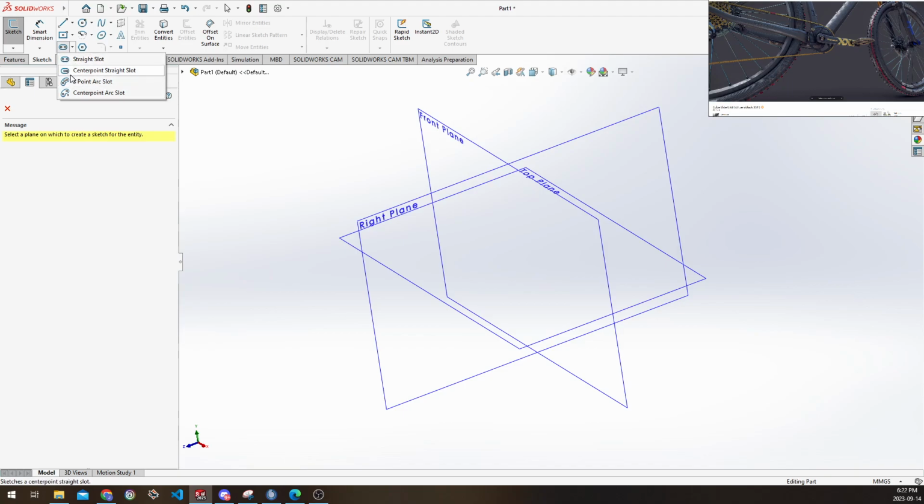These are also incredibly useful. We use slots a lot on this team for 3D printing, because sometimes the parts that we're working with don't have the best locational tolerance. So how we tend to get around that is by creating slots, which allow us to create looser tolerances with our parts, and end up helping us a lot in making sure parts fit together properly.